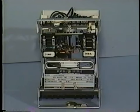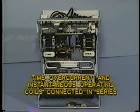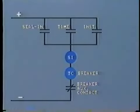Often the time overcurrent relay includes an instantaneous element built into the same casing. As they must respond to the same CT secondary current, the operating coils are connected in series. The instantaneous relay tripping contacts are independent, wired in parallel with the time overcurrent tripping contacts. Thus, in this typical trip circuit, either contact can complete the circuit and trip the breaker.